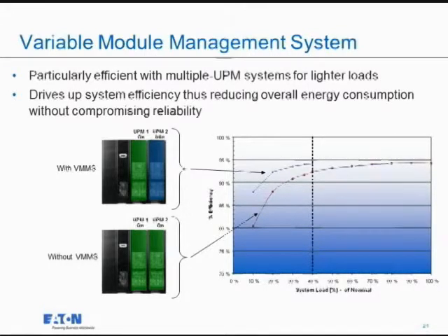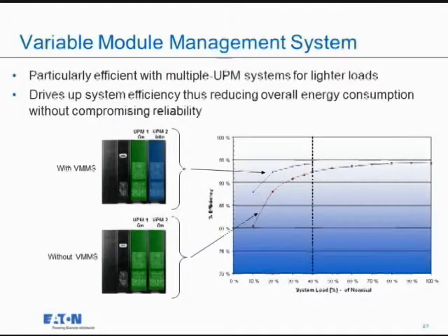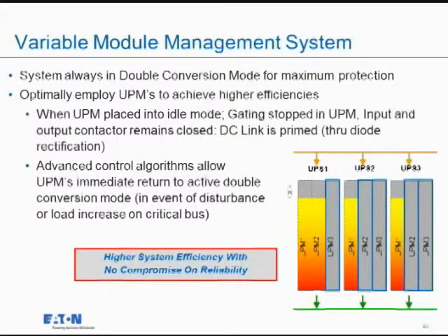It's the runner who's running beside the first person, waiting to jump in. Perfectly in sync, ready to be engaged. We're simply not firing the IGBTs on the inverter. So it's in a hot mode, ready to jump in. So we simply stop firing it, and we get this efficiency savings at the lower loads. When I take a 1.1 megawatt with all of these modules, it's accelerated in terms of my capabilities and what I can achieve.